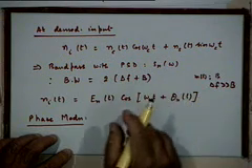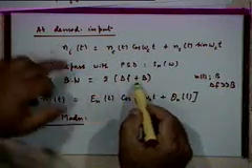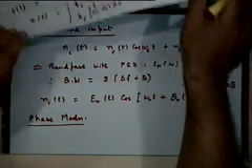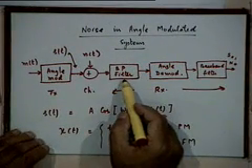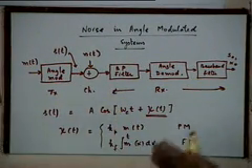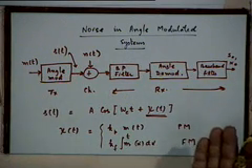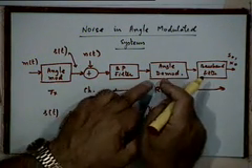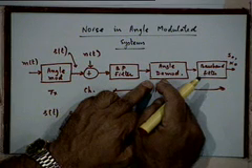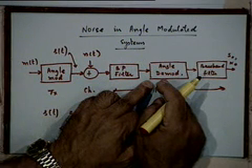But we are passing it to the band pass filter, right? To limit the noise. If I have a very large spectrum for the noise, what I input at the demodulator will depend upon the band pass filter, that is, the bandwidth of my filter. Yes, that's precisely what I am saying. I mentioned this earlier: you have to ensure that the bandwidth of this filter is equal to the bandwidth of the FM or PM signal. If you don't ensure that, your angle demodulator is not getting the right kind of input for demodulation, right?